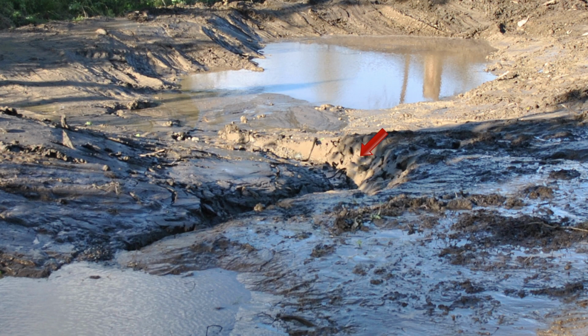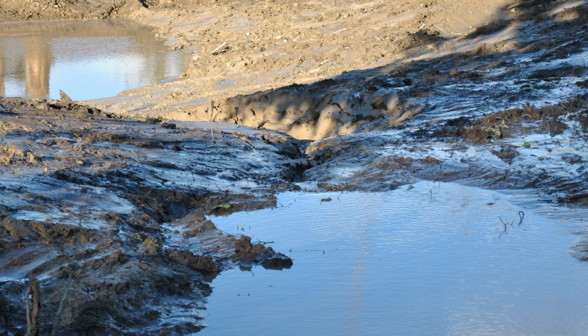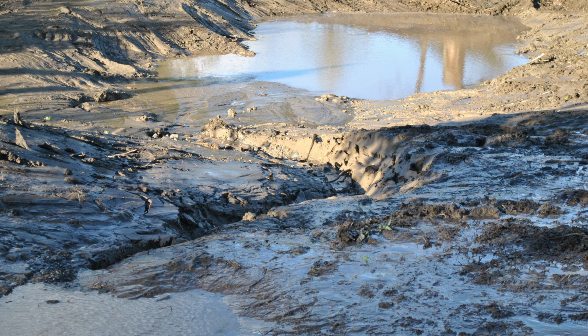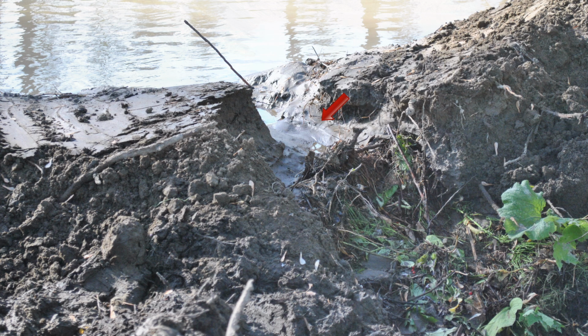We built the wetlands on a steep slope with water flowing from upper wetlands downhill into the lower wetlands. The water flowing out of the upper wetlands quickly caused head cuts to form in the spillway. Because of the sandy soil, the head cuts were carving gullies down the center of each spillway. These head cuts were advancing uphill into the newly dug wetland basin, and they were in danger of draining the new wetlands. Water was cutting channels through the narrow dams that we had built, and these were also draining the wetlands.